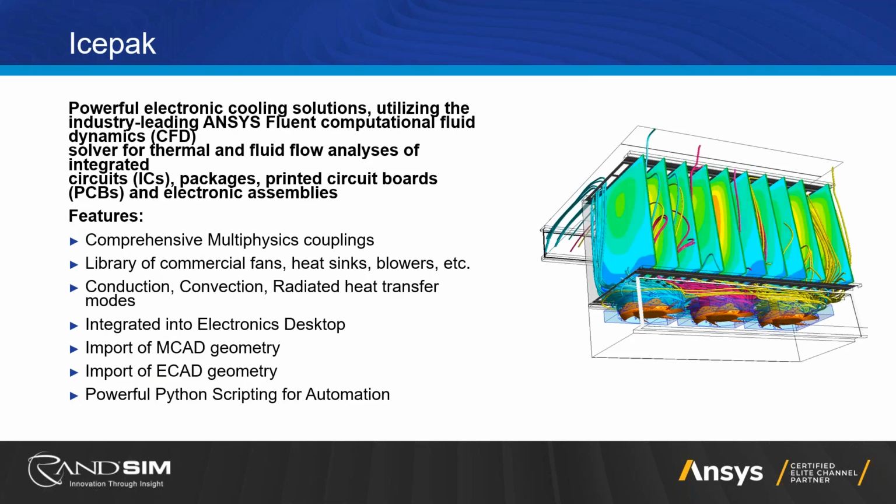Icepak, the other tool I'm going to be discussing today, is the electronic CFD tool. This tool will allow you to simulate your PCB and understand the thermal behavior, as well as, if there are any fans involved, the acceleration and velocity, as well as how that board may be mapped for temperature.